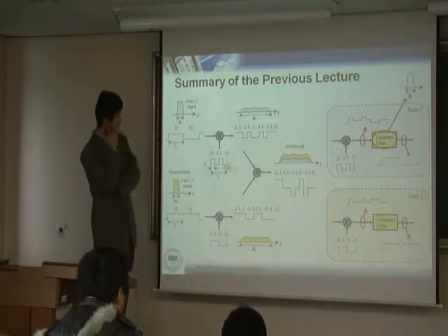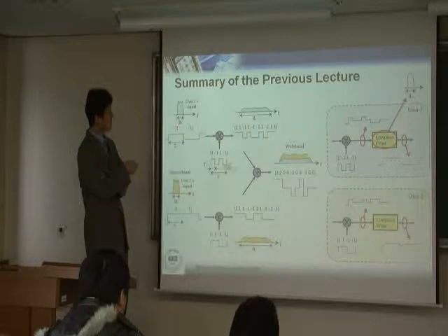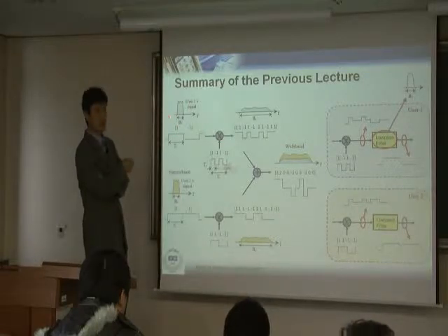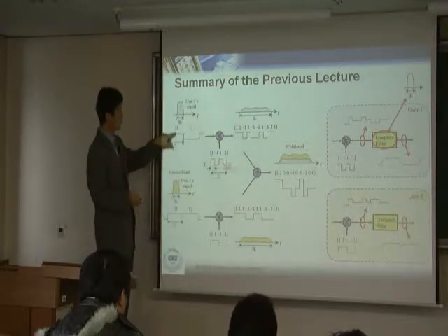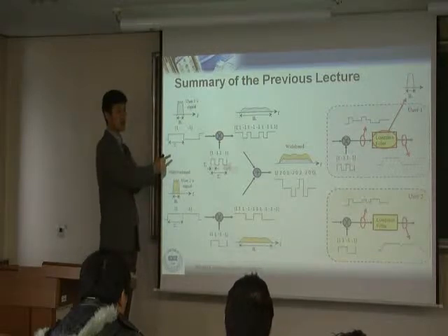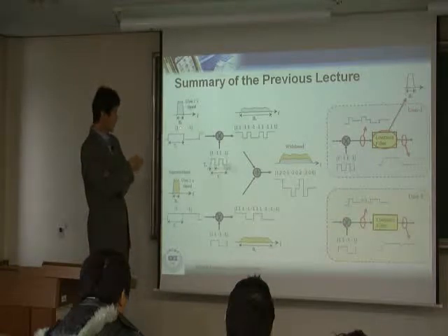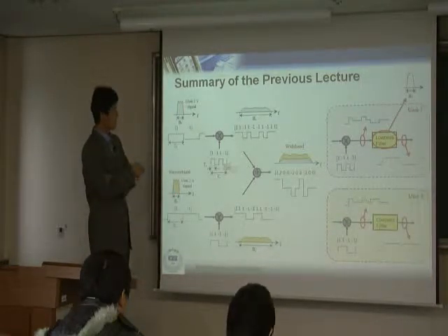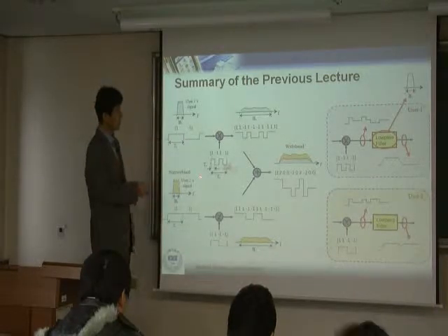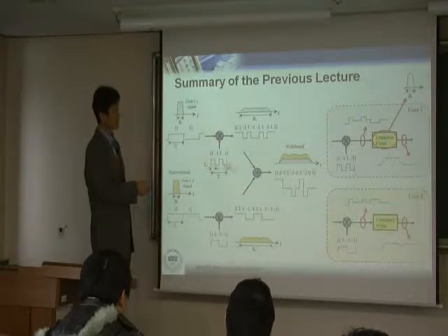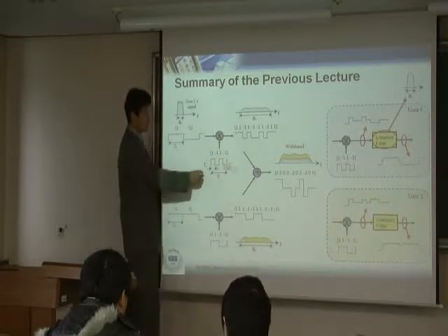This example shows you the concept of CDMA. Typically, in CDMA, the original signal is a narrowband signal. Narrowband means that our bandwidth is pretty narrow, which means that your symbol duration is pretty large. In other words, low data rate, generally. User 2, same thing. But this low data rate or large symbol duration is now multiplied with a fast-rate chip sequence. This is called the chip rate. This is the symbol rate or bit rate. Typically, the chip rate is much faster.